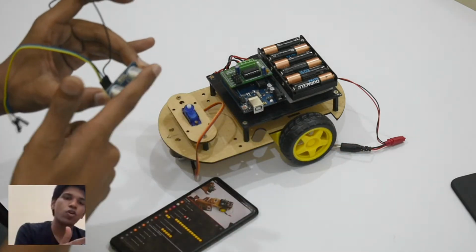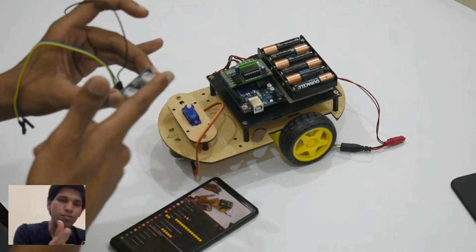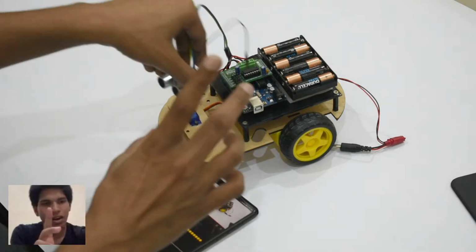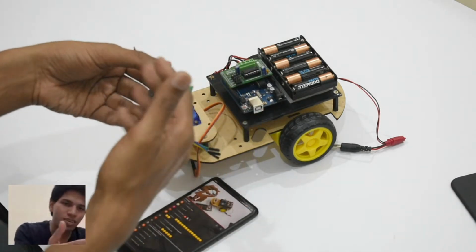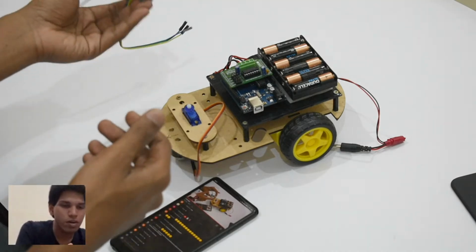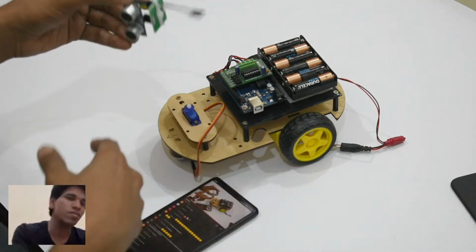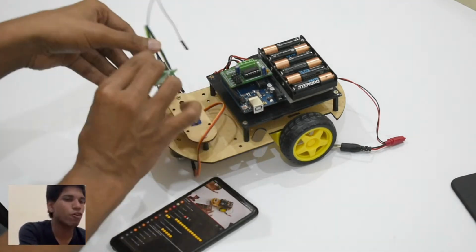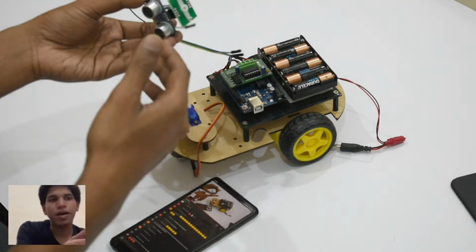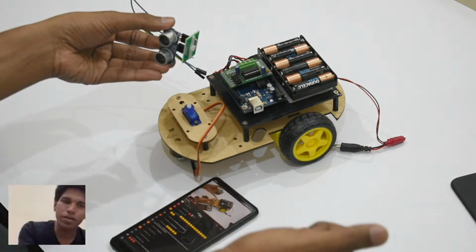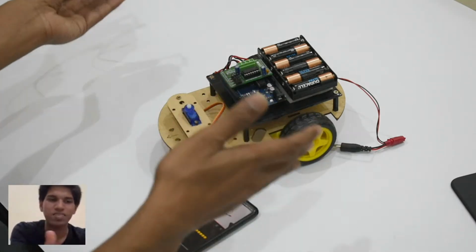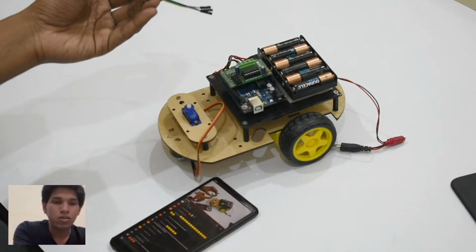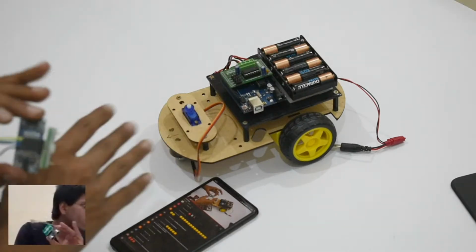Okay, so now that it's able to calculate the distance, we can tell our car that if the distance is less than, let's say, 15, 20, or 50 centimeters, then stop moving and check for obstacles on the left or right side. Then calculate the similar distance of obstacles on the left and right side, and wherever it has more space, it will turn to that side and move in that direction. It's as simple as that.